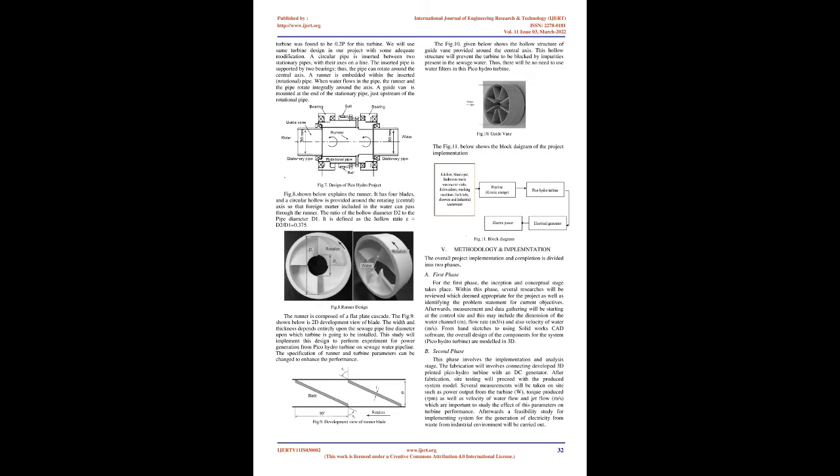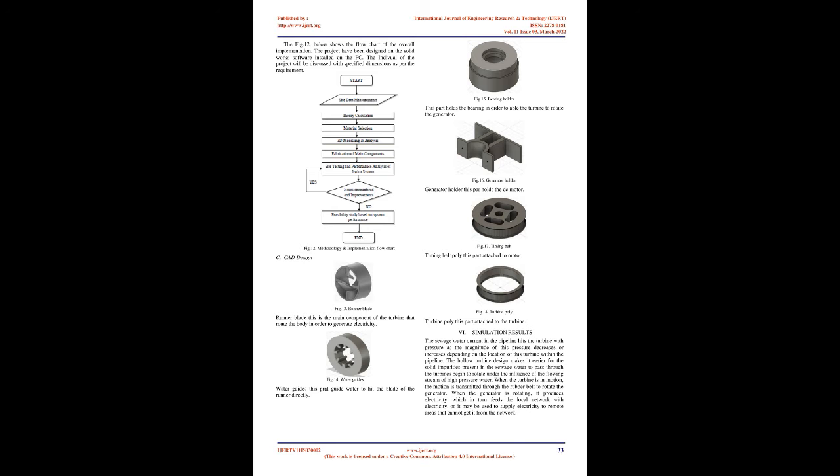The head of the overhead tank was 14 m and discharge was 9 L/s. It was observed that at an average flow rate of 8 L/s, the maximum power produced by this turbine was 212 watts. Riesdoen et al.'s work came out with the description of initial testing on a Picohydro prototype. This prototype was installed on domestic pipeline supplies, using water kinetic energy to produce electricity without disrupting the water supply that is being used for cooking, laundry, and bath.